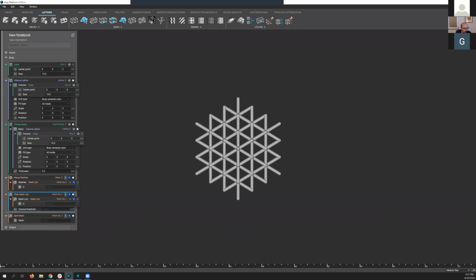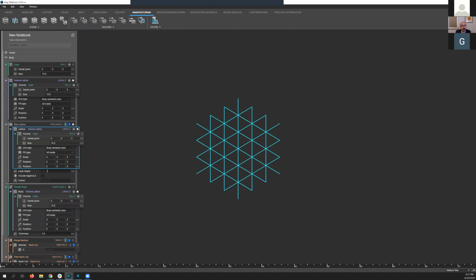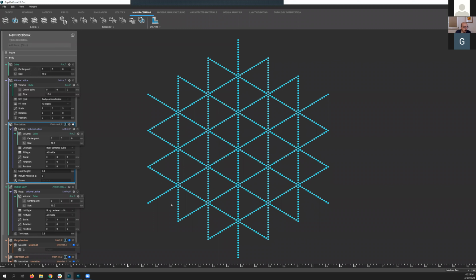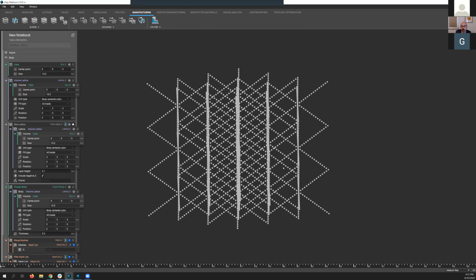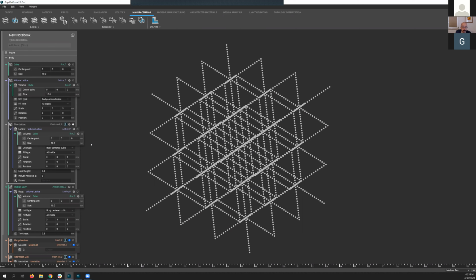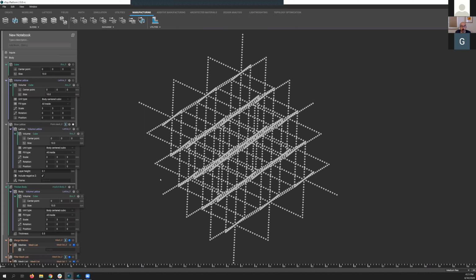So a couple of questions here actually about exporting lattice structure in slices. You can actually go ahead and quickly run through that. Under manufacturing, we're going to have a slice lattice option here. And we can just go ahead. I'm going to specify maybe 0.1 millimeter, and we'll include the negative and isolate. And now you can see we've generated points for this entire graph lattice structure now, quite quickly, quite easily, allowing you to then send that off. You could export this as a CLI file or even CSV data and use that to directly manufacture these complex lattice structures without needing necessarily to go to mesh or even to a solid representation of that geometry.